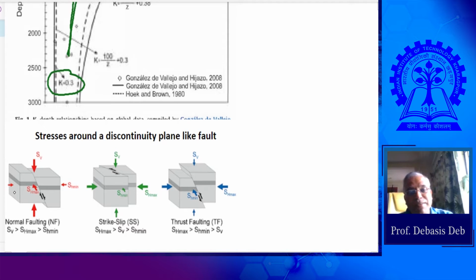So there is a fine balance between the in situ stresses and the kind of geometrical shape you can create under the prevalence of those stresses. If you do not have that understanding, you are bound to go for failure. And that is what this chapter is all about. What is the relationship between shape, size, and the stresses prevailing underground?